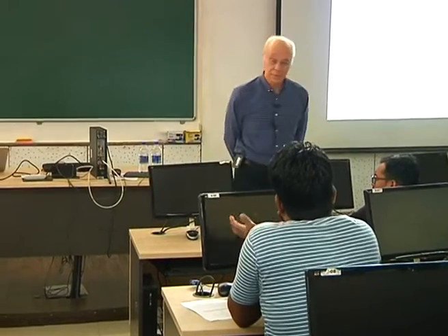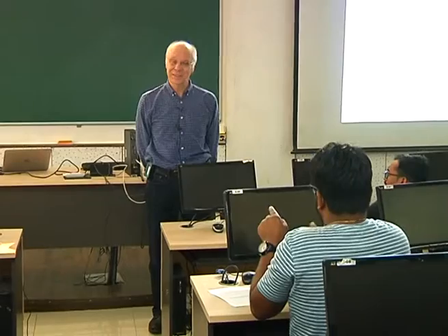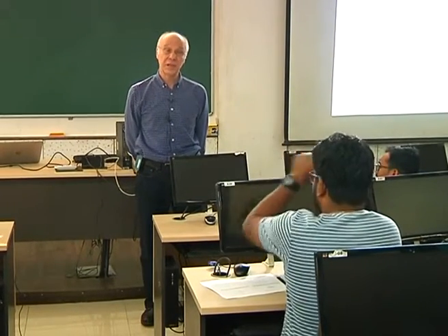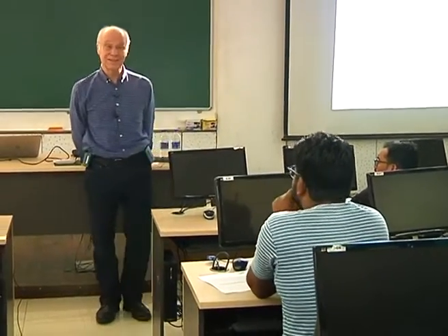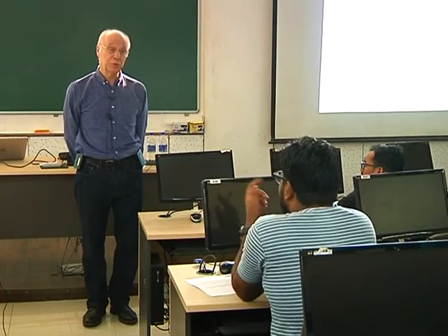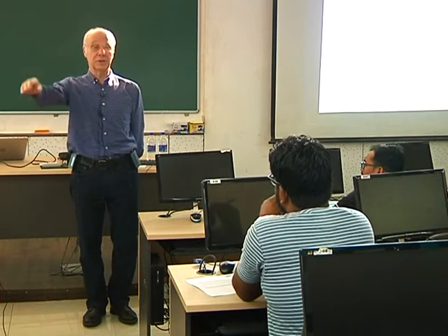Yes? 1/4. A quarter, yes. So basically, normal velocities will be 0 at the boundary. Yes. No, not on the top, because that's the drive. Only on the right, left, and bottom. Okay. And only tangential velocity will exist in the interior. Yes, tangential velocity. So psi will be constant. The stream function will be constant, because there will be no gradient in the y direction for left and right. Okay. Yes. We used that last time. That's the normal velocity. Therefore, psi is constant around the boundary.